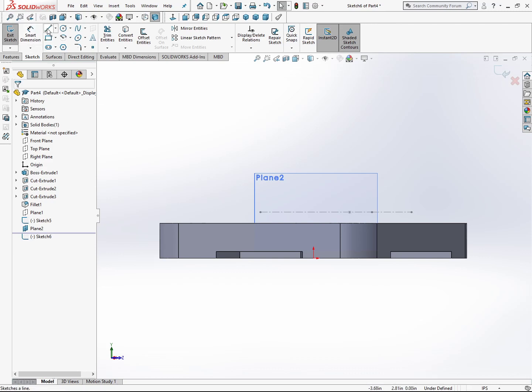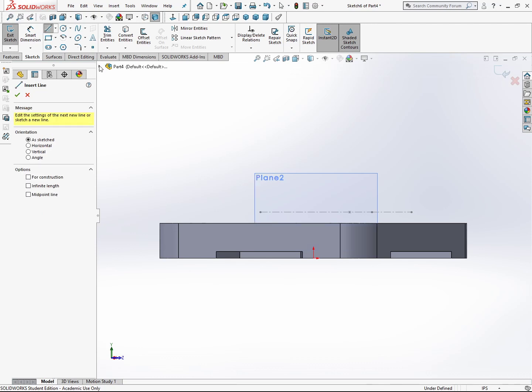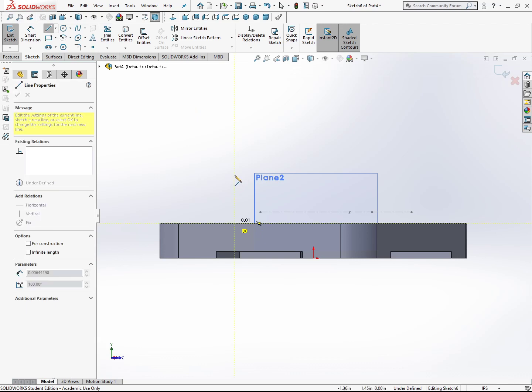We select line and sketch the approximate shape of the angled part from this side that you're looking on, practically the left side, if you look at the task. But while sketching, make sure to hit the fixed point and the start and end point with coincident relations already. So here, just make sure it's coincident.